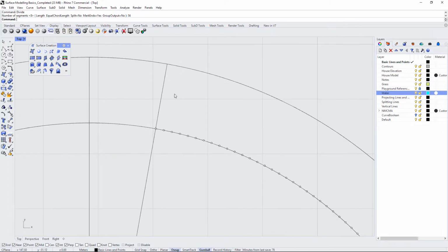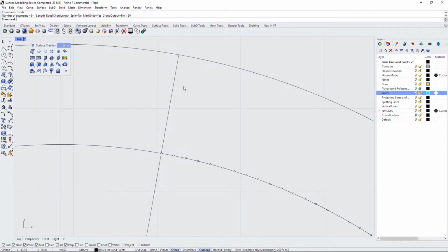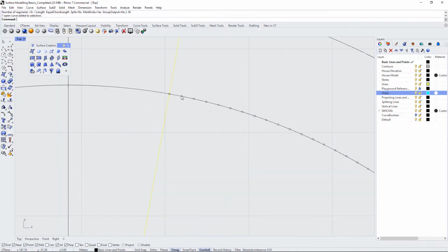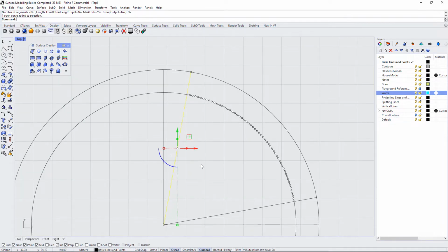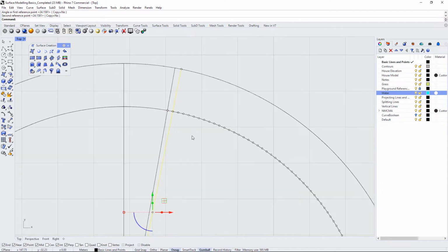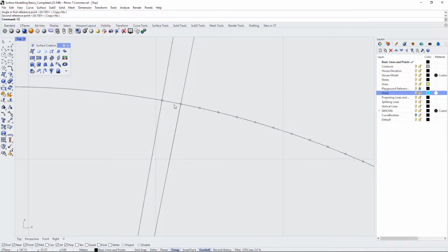So the next thing we want to do is draw a reference object, and we already know that our reference object is meant to be 14 centimeters by 17, and it tapers. So let's first rotate this so that it matches up with this point here. I'm going to use copy and do an in place, and then I'm going to use rotate to rotate this line from here to this point here. And I just want to make sure my points are checked off so that I can match up there. We also know that this distance is 15 centimeters.